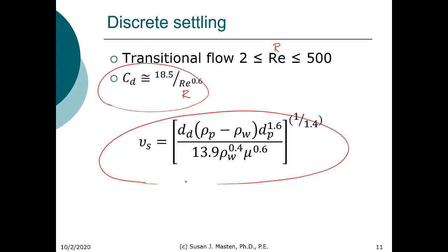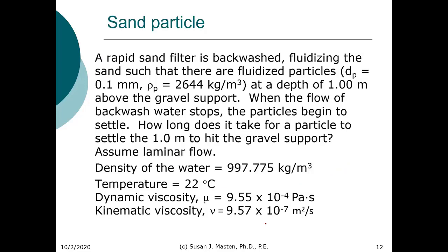So we have multiple equations that we can use for the settling velocity. For the most part, you will attempt to operate in a laminar flow, so the simpler equation should work.